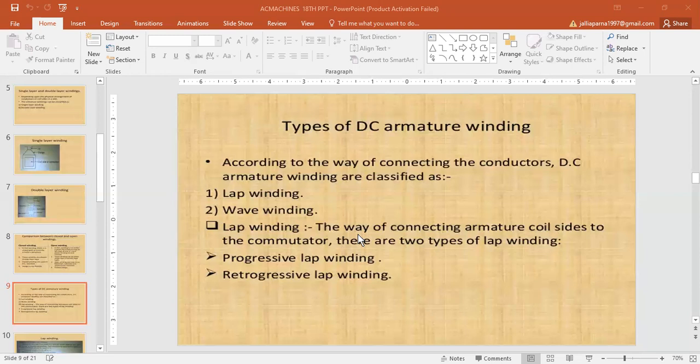Such winding, in which two coil sides occupy each slot, is most commonly used for all medium-sized machines. Sometimes 4 or 6 or 8 coil sides are used in each slot in several layers, because it is not practicable to have too many slots.